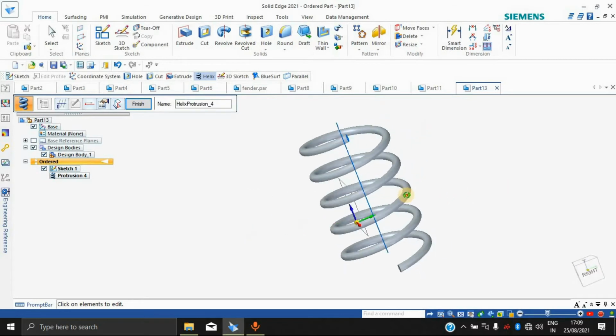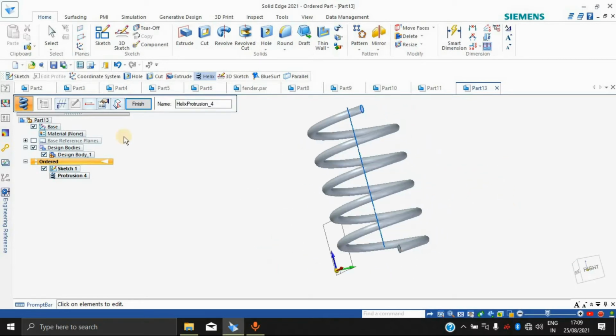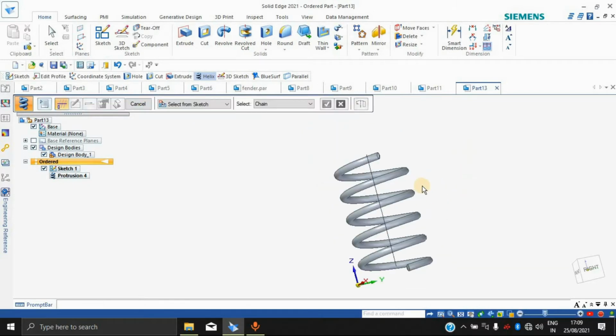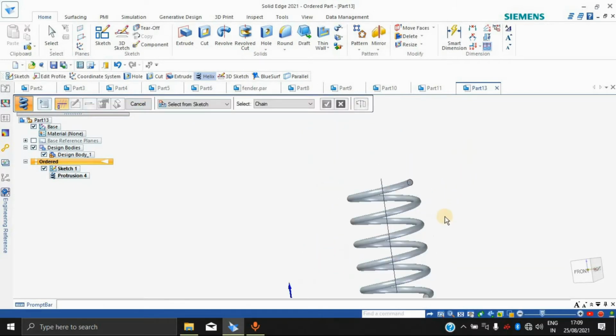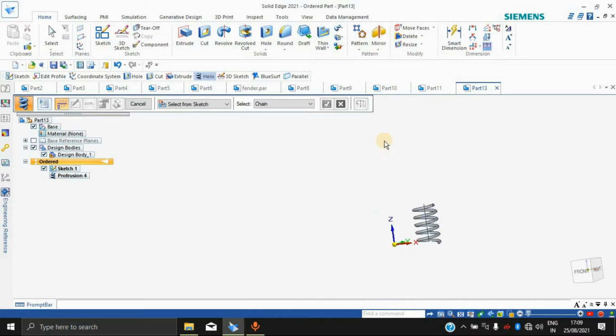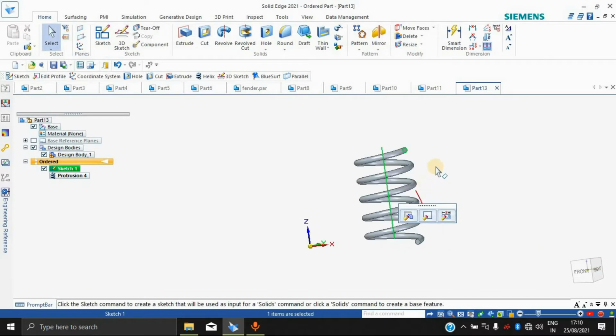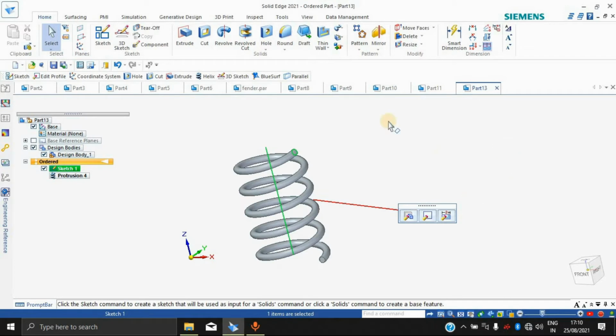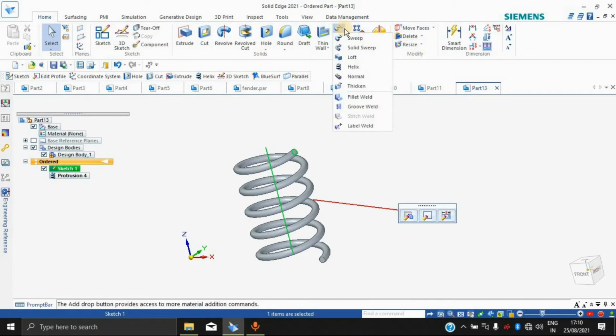So this helix can be formed through many other ways, like in the previous menu we saw, but this is a little bit difficult. Difficult in the sense that while selecting, first you have to select the circle, then click on tick, then select the line twice with a double click, then click on next and adjust the axis length or number of turns as you want. So helix is complicated, not hard, just complicated. We'll see what is left.